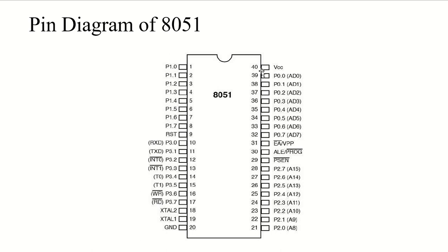And finally, pin 40 is the VCC, which is used for power supply, which is used to provide the power supply to my microcontroller circuit. And that would be the pin diagram of my microcontroller 8051.